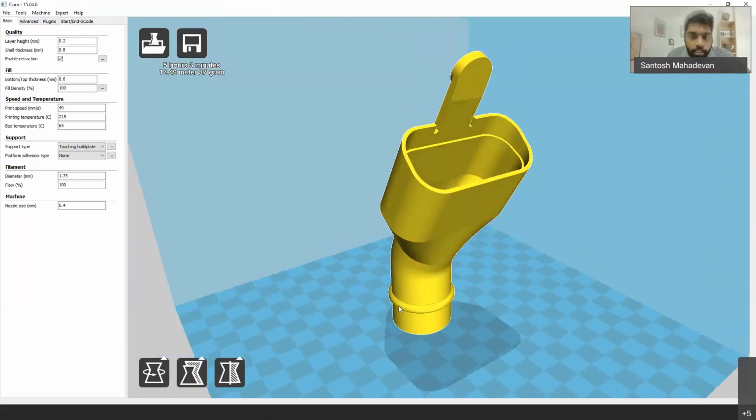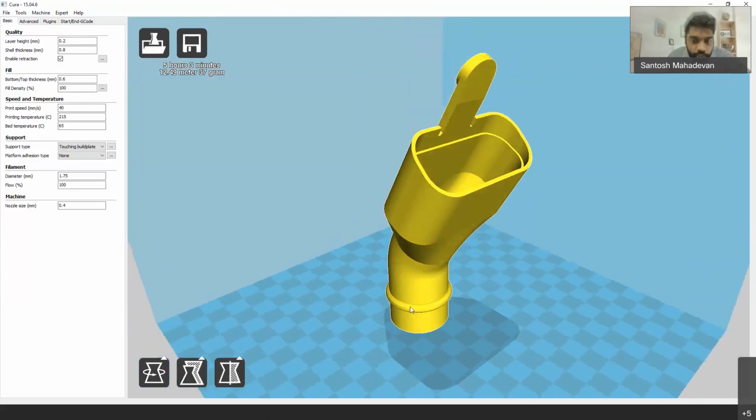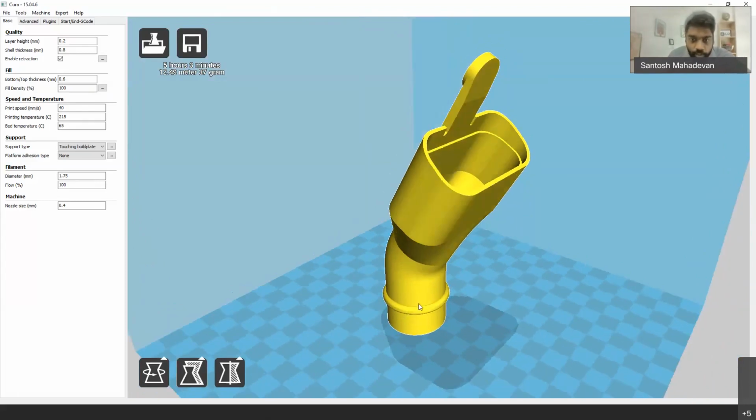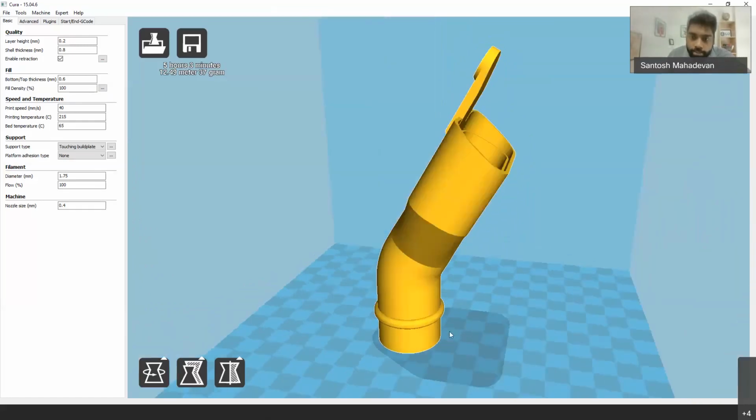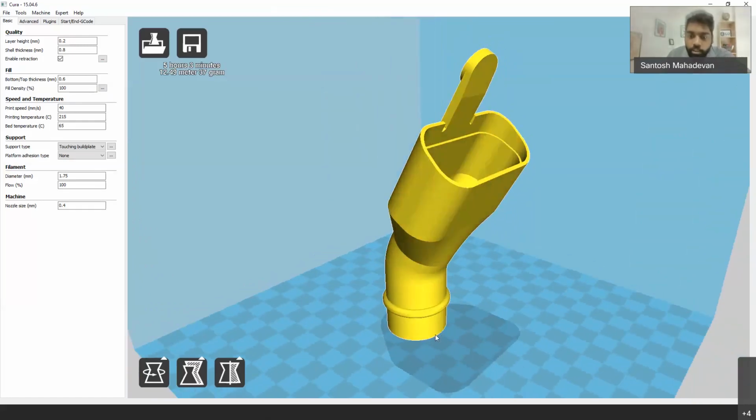Regardless of the 3D printing method, whether it be laminated object manufacturing, selective laser melting, using powders, using wires, or even using photopolymers, the fundamentals remain the same: you are always going to process the material in a way that you deposit or stack layer upon layer upon layer.